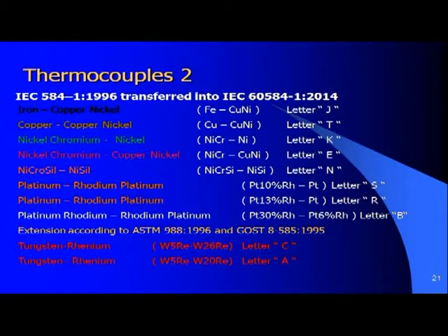So depending on the temperature gradient in your furnace and the speed of heating up and cooling down, the rhodium moves, and this causes inhomogeneities and drift effects in the platinum-rhodium thermocouple type S. This effect is much less in type R. So most of the laboratories, for their standards, now use type R thermocouples instead of type S because of higher stability and fewer problems with inhomogeneities.